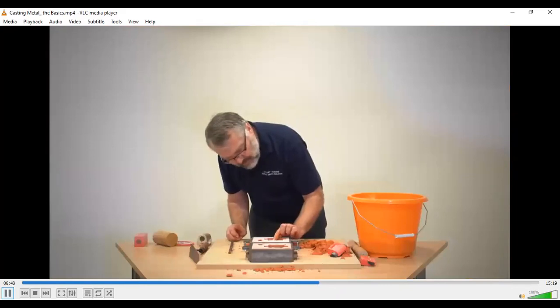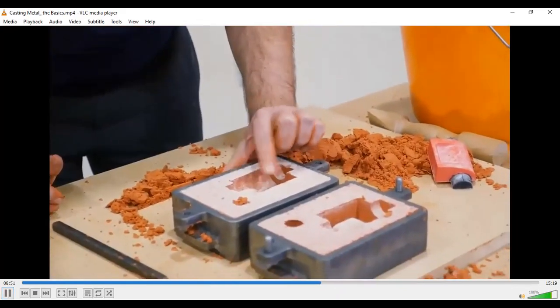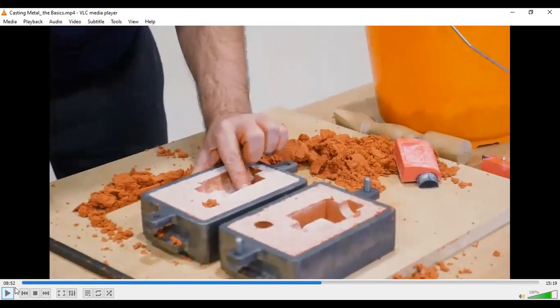That's come out quite well. There's a little bit of looseness there. Nothing to worry about. Right, if you observe, he gave a little tap, just so that the dimensions of that cavity would increase a little bit. That's common sense. So when we are deciding the size of that pattern, that allowance has to be there. To have it removed easily, we have to give a tap, and that tap will increase the dimensions. So that allowance has to be given, that you will make this pattern a little small.